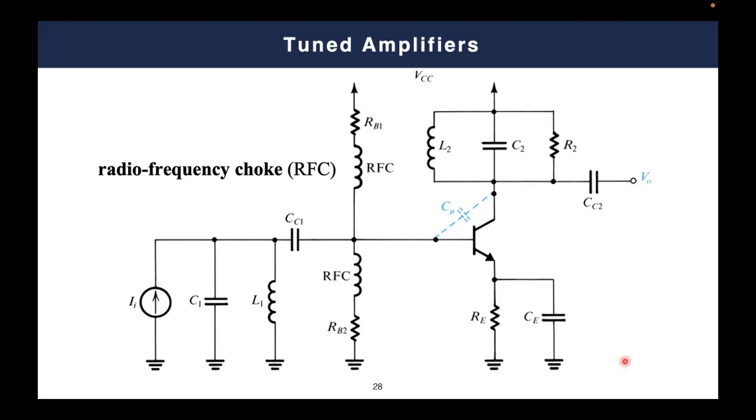By the way, we have another bypassing capacitor, which is CE, I forgot to mention. It typically has the same behavior as CC1 and CC2, because it will show an open circuit during the DC analysis, so that now you have an emitter resistance and an emitter voltage value, this VE voltage. Alternatively, in the AC analysis, it will behave like a short circuit.